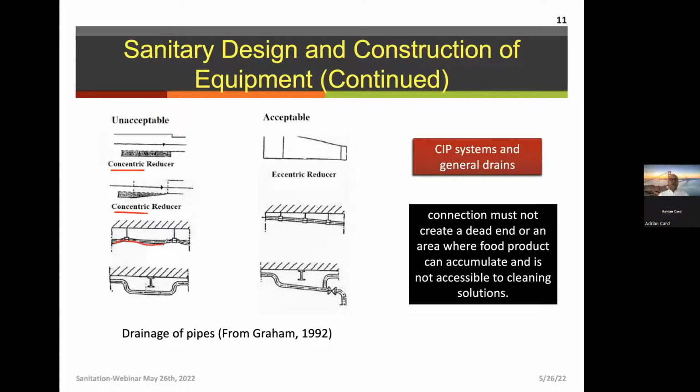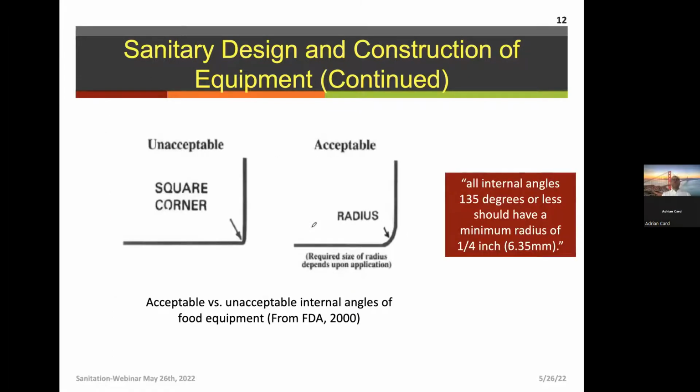And therefore, if we're going to try to treat this with any kind of residues, in these areas, or in this corner here, is where all the accumulation is going to happen. So we need to make sure that they are at a certain inclination, okay? There are specific values associated with these pipes that prevent that specific accumulation and permit specific controls, not only to prevent accumulation of the liquid, but also to prevent accumulation of the sanitizers.